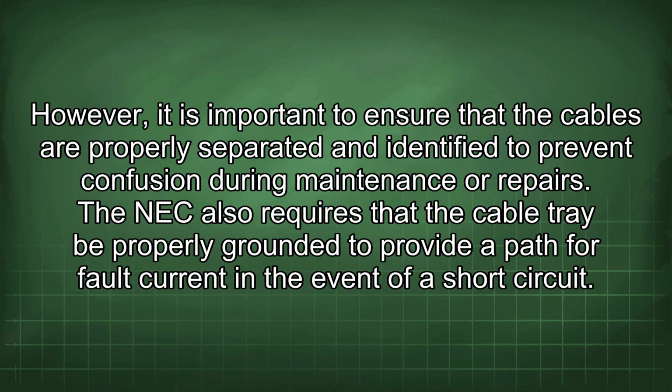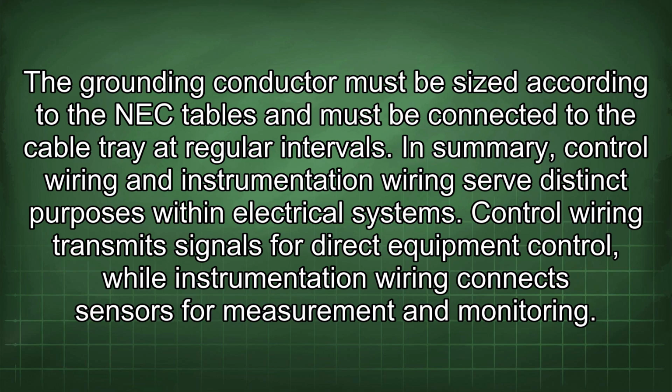The NEC also requires that the cable tray be properly grounded to provide a path for fault current in the event of a short circuit. The grounding conductor must be sized according to the NEC tables and must be connected to the cable tray at regular intervals.